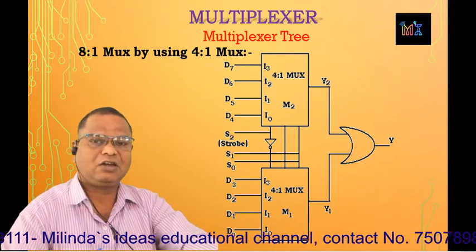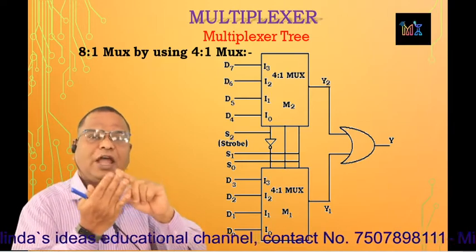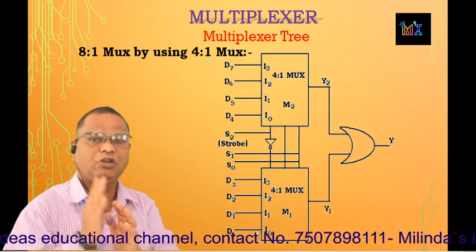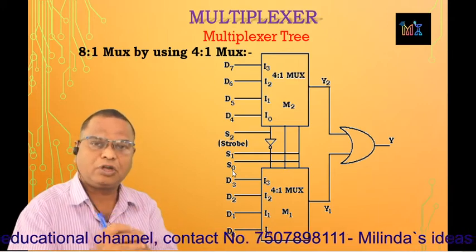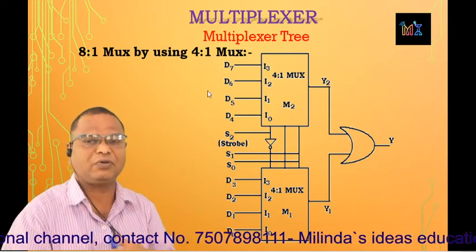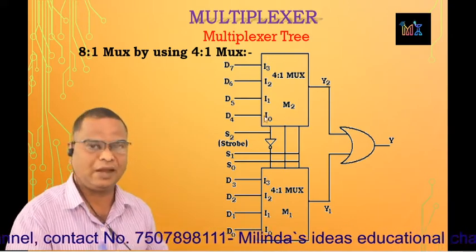As there are 8 input lines, that is D0 to D7, the inputs D0 to D3, the data inputs, are connected to the input terminals I0 to I3 of the lower mux, while the data inputs D4 to D7 are connected to the input terminals I0 to I3 of the upper mux, that is M2.